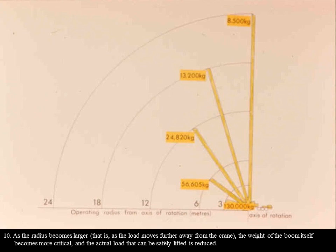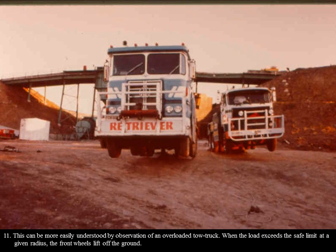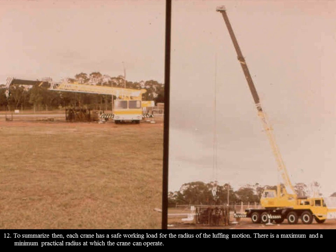As the radius becomes larger, that is, as the load moves further away from the crane, the weight of the boom itself becomes more critical, and the actual load that can be safely lifted is reduced. This can be more easily understood by observation of an overloaded tow truck. When the load exceeds the safe limit at a given radius, the front wheels lift off the ground.